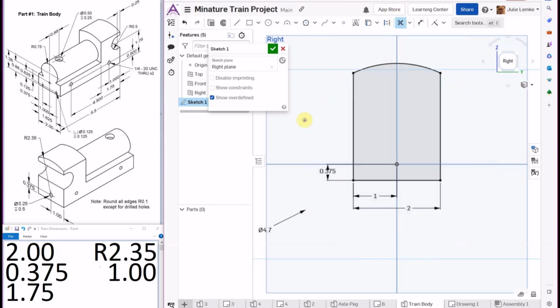So I'm going to trim off this extra, and you can see how this dimension still moves around and everything, but it was pointing to the middle of nowhere. If you want, you can move it over to there so you can see what it's actually referring to when you go back to your drawing later if you need to.